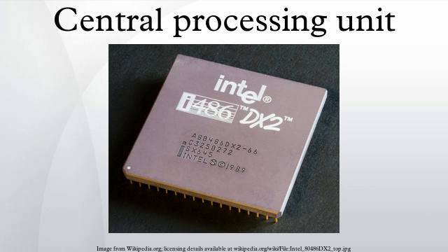In many CPU designs, an instruction set will clearly differentiate between operations that load data from memory, and those that perform math. In this case the data loaded from memory is stored in registers, and a mathematical operation takes no arguments but simply performs the math on the data in the registers and writes it to a new register, whose value a separate operation may then write to memory.